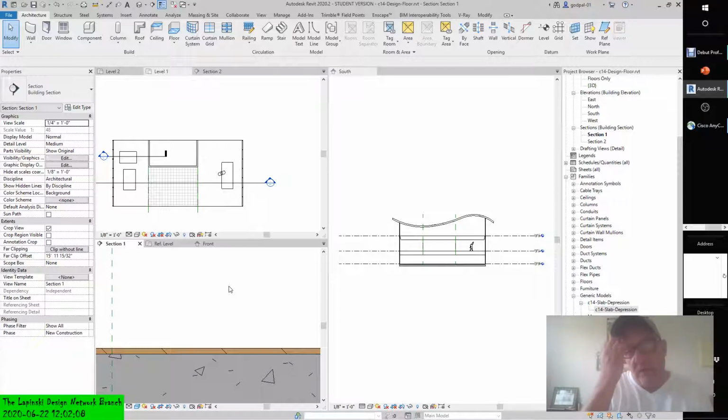And the whole floor doesn't have to be pitched in one direction. On one floor, you can have multiple areas or multiple perimeters that pitch different ways. Just like a roof, right? Just like a roof. The object is just to get the water out using gravity.